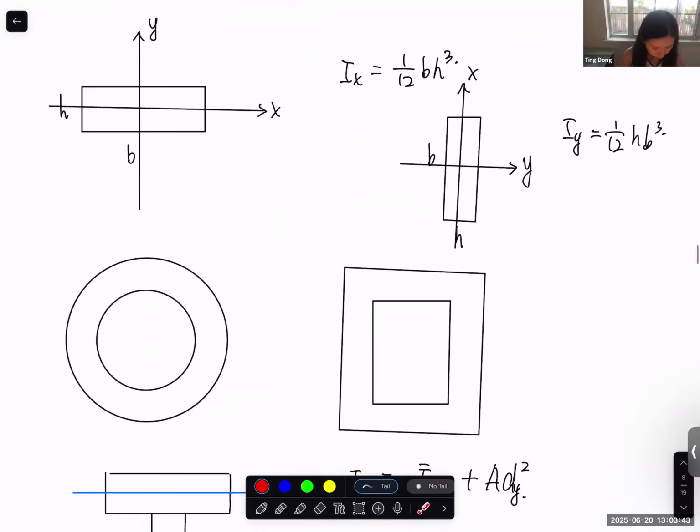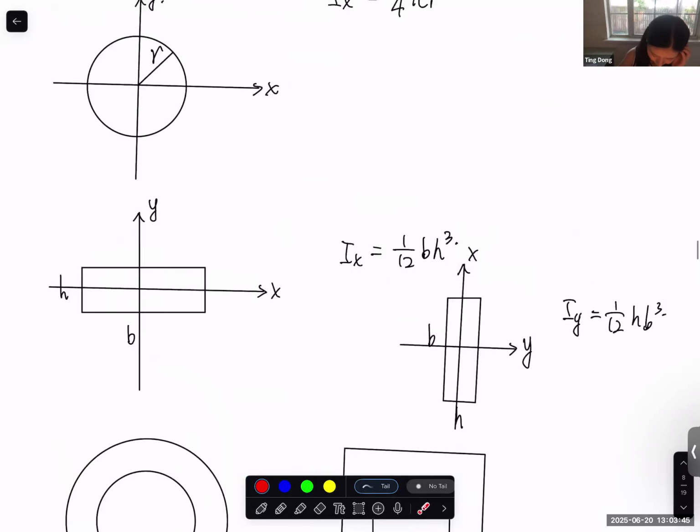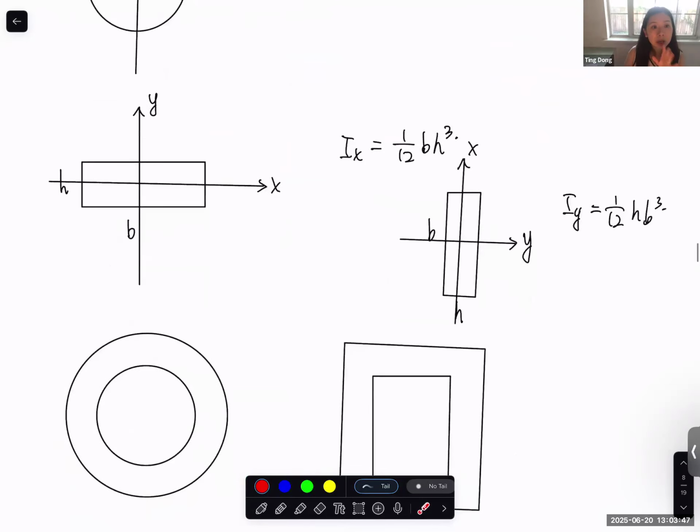And we talk about the moment of inertia, how to calculate moment of inertia, and the thing you need to be careful of when it's a narrow rectangular cross section, because bending about different axes, the way you calculate the moment of inertia is different. You need to know which axis it's bending about and what the b and what the h are. bh cubed, which one you need to use the cube on.